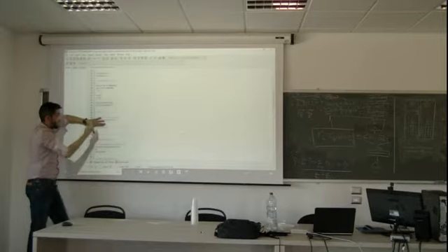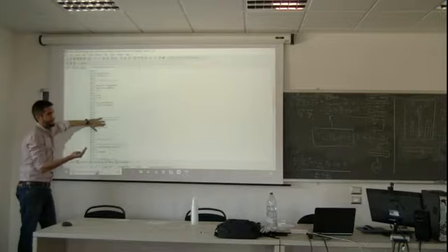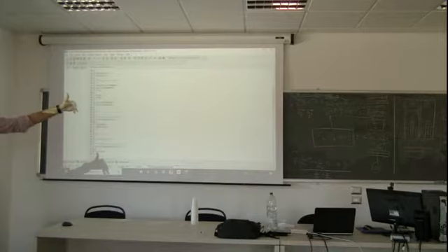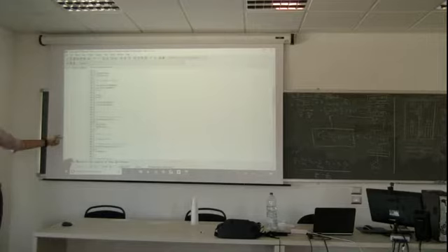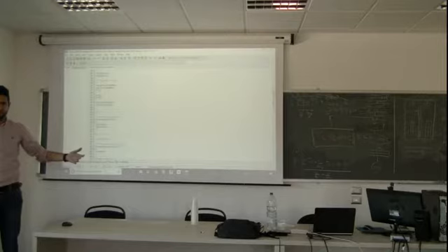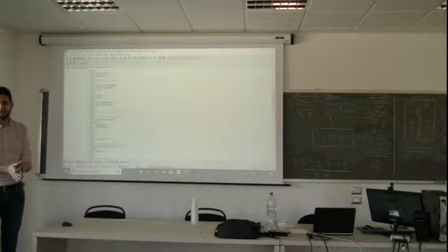Okay? So now, what I recommend is to start with some value that you know will be around. I mean, there will be some nodes that will be close to 25. The ones closer to the surface, maybe will be 26, 27, they will be closer. So it's not a bad shot to start with 25. So let's start everything with 25. If you want, you can start here with a linear profile. Whatever you like. It will reach convergence anyway.